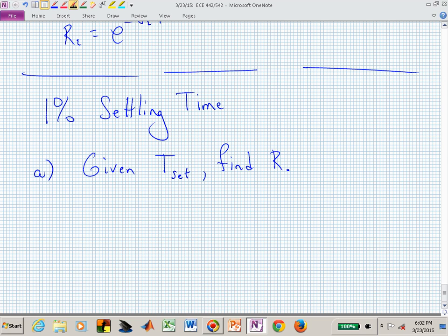And during this discussion, I might use the following. If somebody gives me the numerical value for settling time, maybe half of a second, I might want to translate that relative to my sampling period, or how many sample periods that represents. So I might represent that as capital N sub s times T, where T is the sampling period.